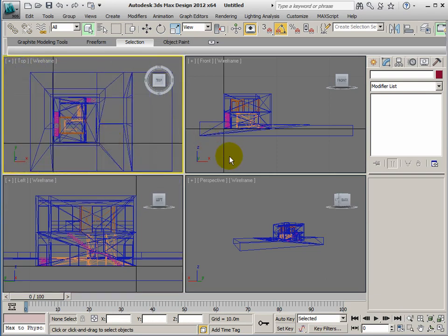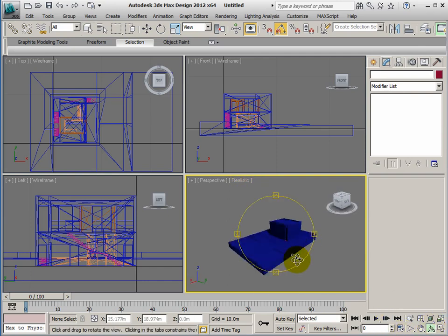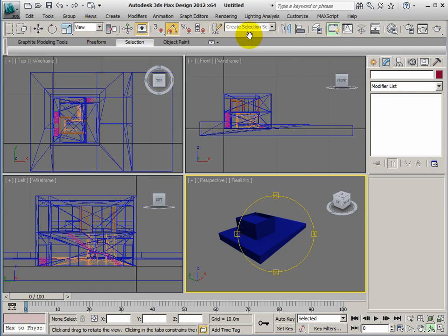Okay, so we've got the model in, and we've got our heads around the orientation. I'll set this one sitting at a realistic shading setting, and you go, oh, that's not looking too great. All this is just the line colours being translated into a material colour. So what I'm going to do is create a material just to apply to the whole lot. We just want to pick out the solid from the void. So we'll just go for white paint and glass.